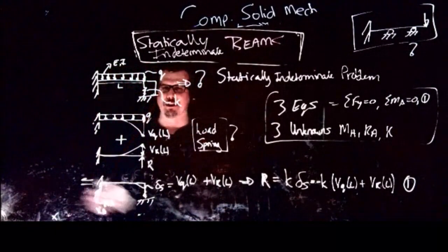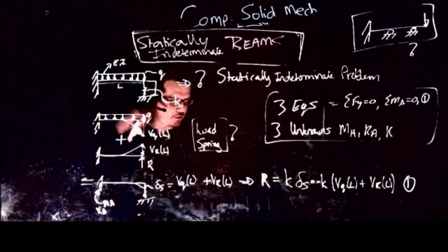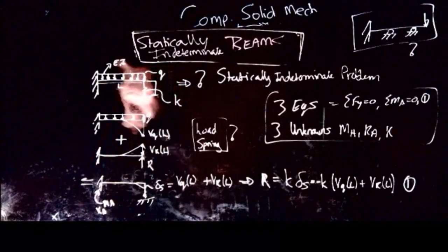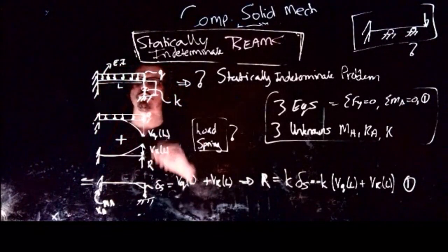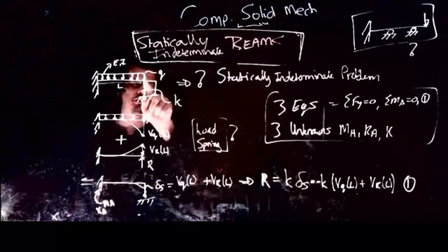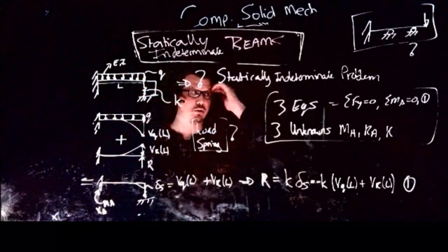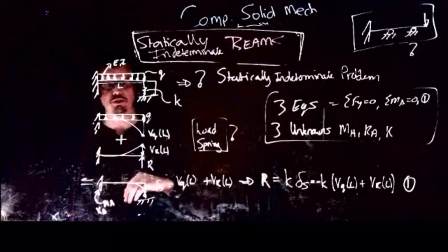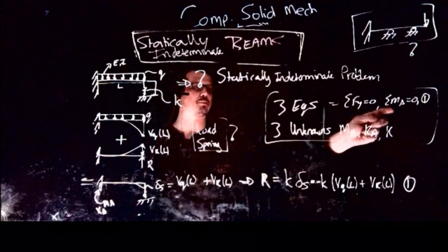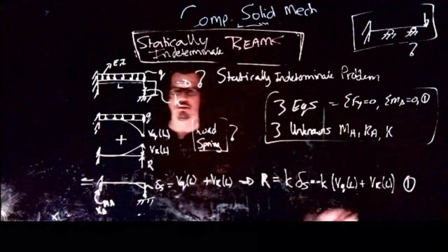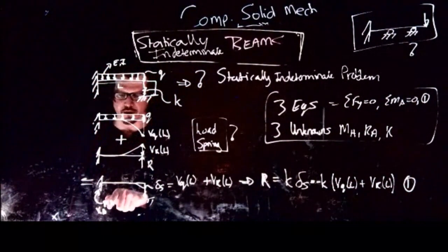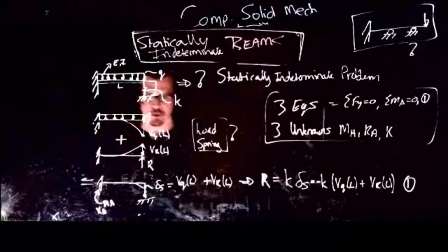All right, so where were we yesterday? Yesterday we just started to talk about the derivation in terms of this little example problem. Let me recap where we were. We had this clamped beam with a distributed load Q, and this spring inside here. When we looked at the number of equations and number of unknowns, we realized that if we look only at the equilibrium equations, we only had 2 equilibrium equations. So we needed a third piece of information, which is what we derived to help us solve this problem, because the unknowns were the reactions RA and MA, the reaction loads, but also the force in the spring.